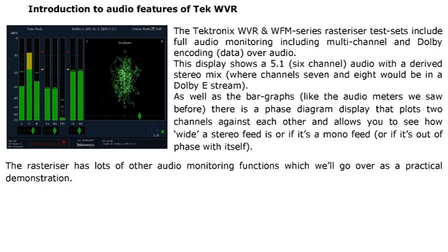And then as well, we also have a stereo mix that's made inside the Tektronix as the next two bars, because I think most broadcasters appreciate that even though they're putting their program out in glorious HD with 5.1 surround sound, an awful lot of people will be watching it in SD with only stereo audio. So it has to sound good and look correct. It has to conform in both standards. So the Tektronix is very helpful in making a stereo indicator of the 5.1 surround.